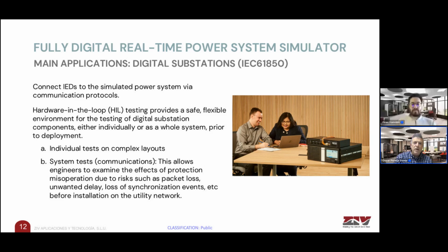For example, one very clear example is, imagine an automatic voltage regulator, an AVR for transformers. You want to validate the behavior of your AVR for a situation of 5 power transformers working in parallel. This is not that easy to test for real on the site. So for that, this RTDS power simulator is very useful. We can virtually create or emulate 5 power transformers in our system, even being the same, the 5 equal or different.